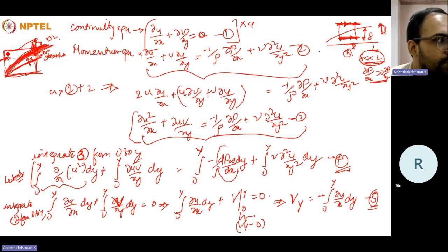So it will be slightly tilted upwards to take into account the loss in mass flow rate. So the same mass flow rate will be felt at a higher distance away from the wall. And for that to happen, there should be a y direction velocity across the streamline. So that's why we say that the y direction velocity is not zero at the boundary layer, and hence it's not a streamline. There will be flow across the boundary layer.